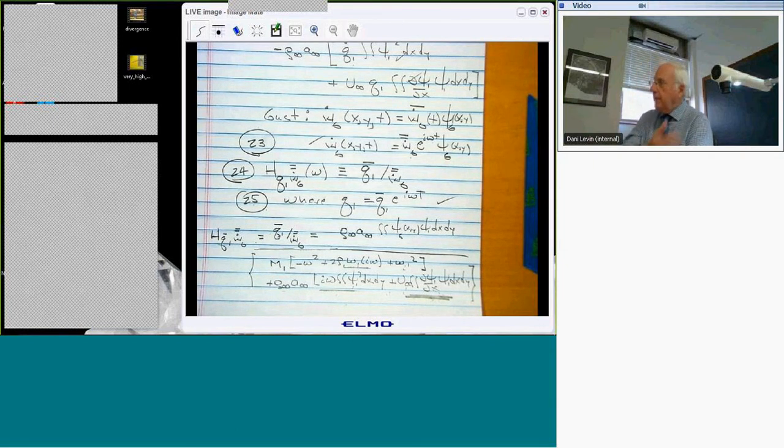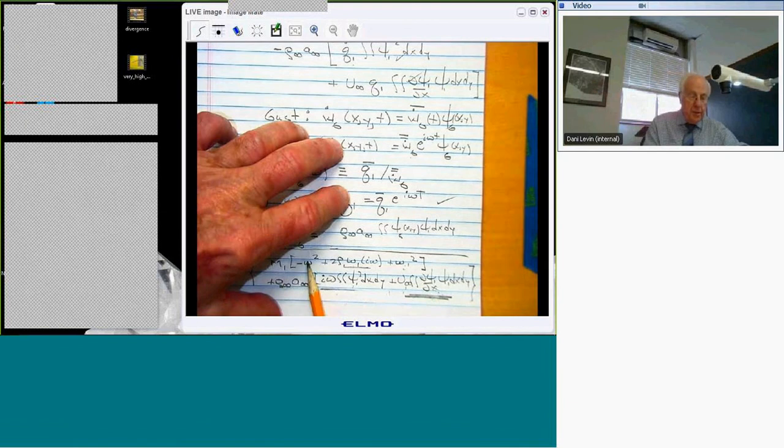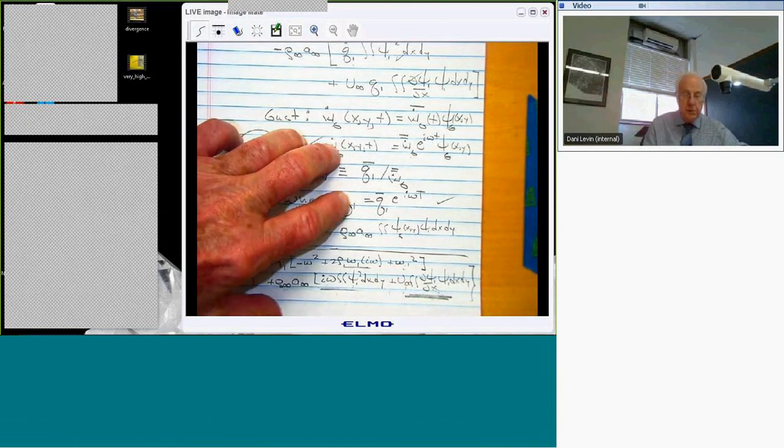You can have negative damping. You can also have negative stiffness due to the aerodynamics. I mean, that's really what divergence is all about. It's all about the aerodynamics creating a negative stiffness, which offsets the positive stiffness from the structure, and then you have the static instability. And of course, the static instability frequency is 0, right? And so if the frequency is 0, those terms go away.